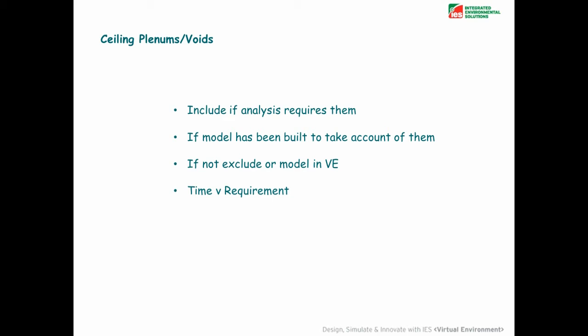So you can include them, as I've mentioned, by just putting in the levels in your model, so having ceiling level for ground floor, ceiling level for first floor, and just tie your room or space to these levels. The other option would be just don't take account of them within Revit and just create them within the virtual environment once you get across, or just exclude them and account for them within the construction within the virtual environment.